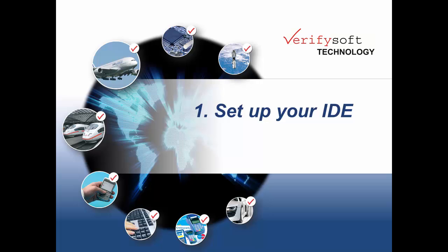The Code::Blocks IDE is quite simple to use. I will show you how to integrate it as a normal IDE. To do this, we will edit our compilers. Normally, you can integrate the AVR compiler quite easily, and how this is done, I will show you now.